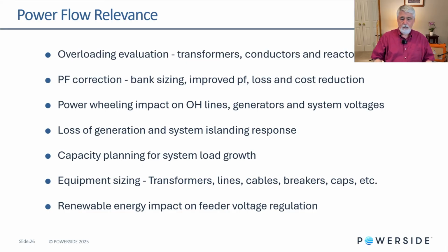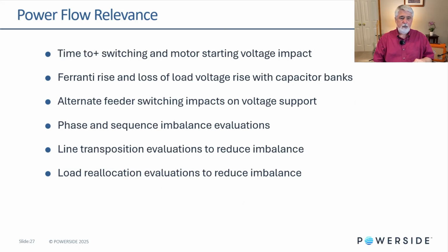Equipment sizing. Use a power flow to determine alternate switching conditions, things that might overload equipment. You can perform those in a power flow solution because these are steady state conditions that are being considered. Renewable energy impact on feeder voltage regulation. We mentioned that just previously.